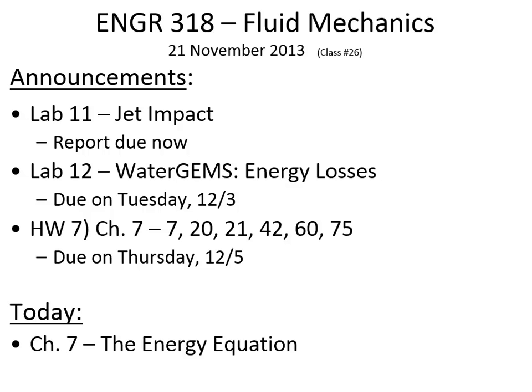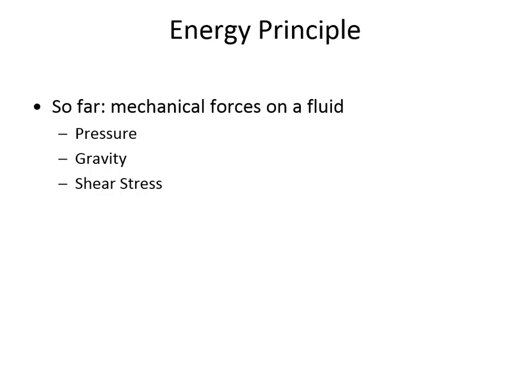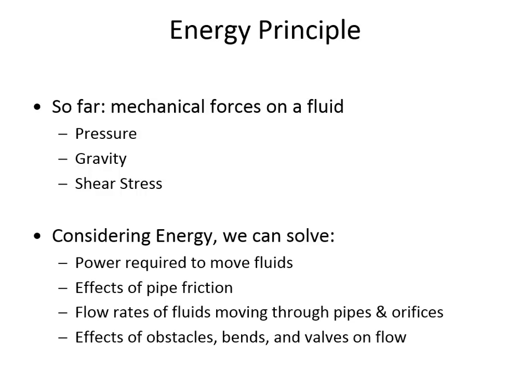And so anyways, we're talking about the energy equation today. It allows us to get away from some of the limitations that we've had in calculating the forces and the pressures associated with flow movement. We've talked about different types of forces on a fluid, like the pressure forces that accumulate when a plane or a curved surface is submerged underwater. We've talked about, for example, shear stress when 2 plates are moving over each other, or even the shear stress of flow inside of a pipe.